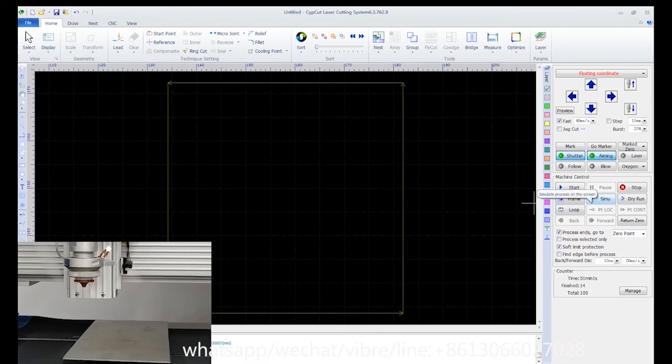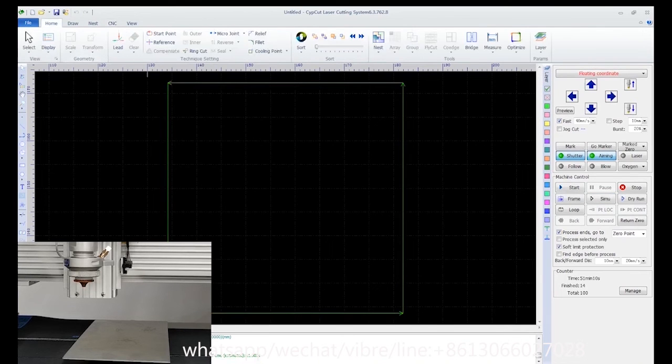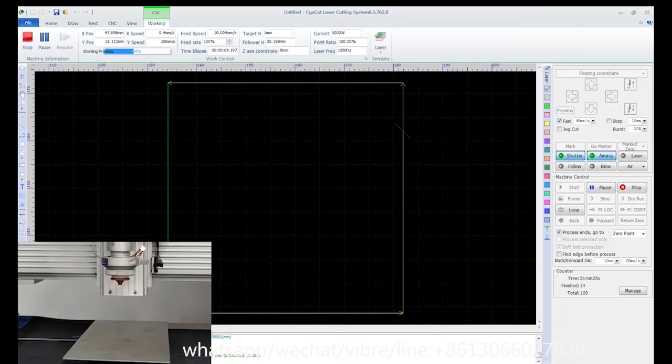We can check the cutting path by this simulation. We can change simulation speed above in the menu bar. It only demonstrates sequence in drawing, and doesn't execute any motion commands in the machine. Dry run is to travel along the designed tool path, not cutting it.